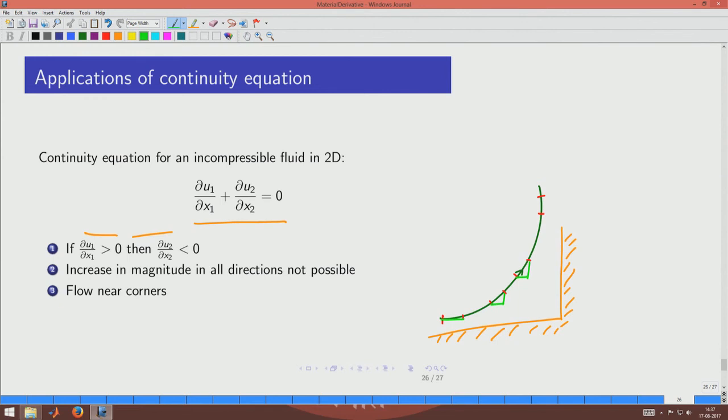You can see that here the x component of the velocity is much smaller, here it is in between, and this is full, and the y component is actually 0 here, it increases, and here it becomes fully y. So, if you take this direction as x1 and this direction as x2, then dou u1 by dou x1 is negative, because the x1 velocity is decreasing to 0.